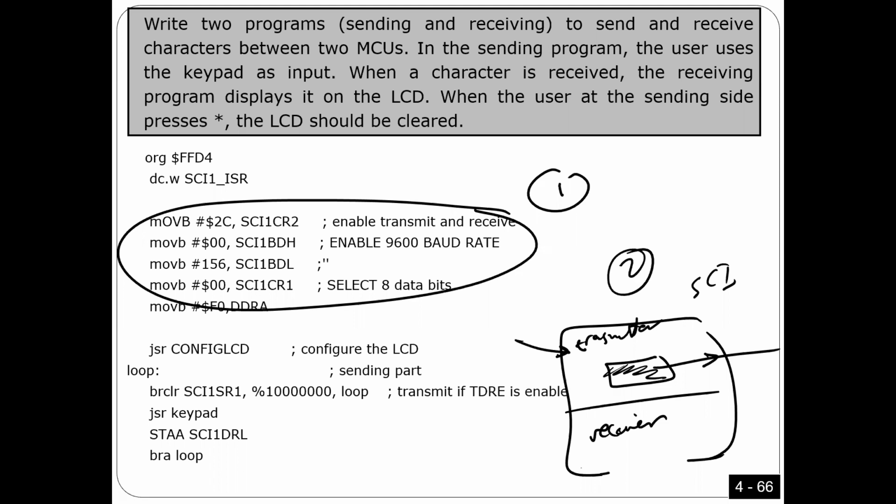To transmit it. So all what you have to do, number 1, I have to make sure this one is empty. Number 2, once I know it's empty, I'm going to write a byte to it. That's what I did here. How can I know it's empty? Because you cannot overwhelm the transmitter with take this data, take this data, take this data. Because the microprocessor is faster, before I give a new byte, I have to make sure the transmitter already finished the last one.